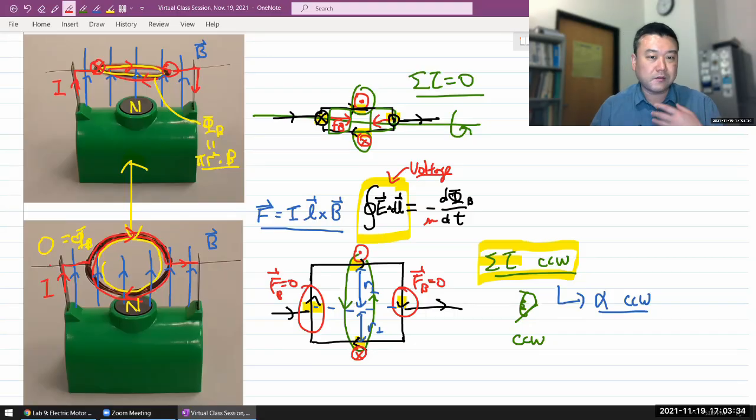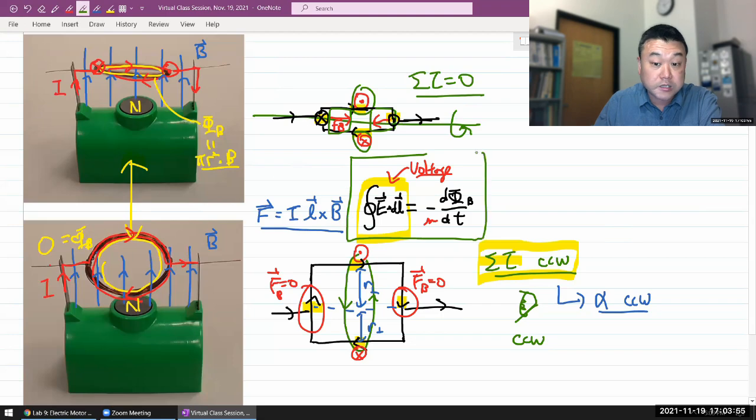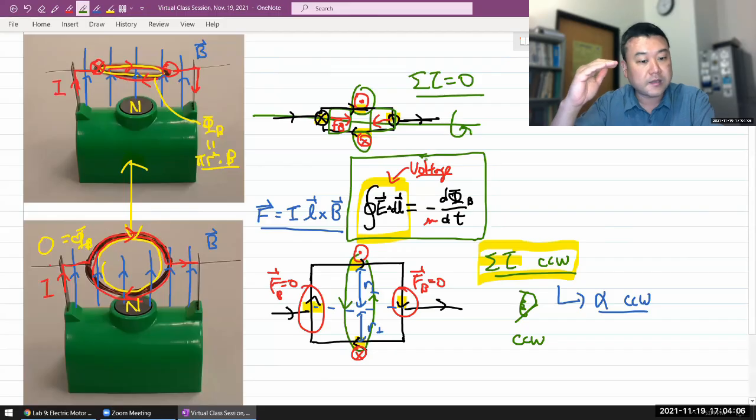Or in the case of a more realistic motor, the only amount of power that needs to be drawn is the same power that's needed for the motor to do mechanical work, either against the friction or against the load that you are imposing. This part of the operation of a motor is important because this makes it so that a free running motor is safe. It has some natural maximum speed that it'll run to that depends on the magnetic field and applied voltage. So the applied voltage acts as a natural regulator. It limits how fast the motor can spin.